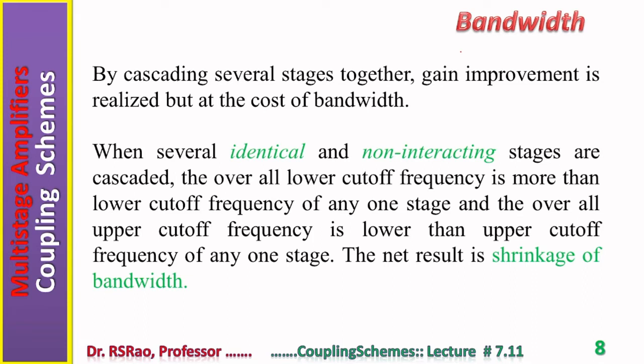Sometimes it is a more significant parameter than gain. Bandwidth is a frequency domain specification. In time domain, it is indicated by rise time. More bandwidth means less rise time. More bandwidth means fast response. Less rise time also means the same thing, fast response.